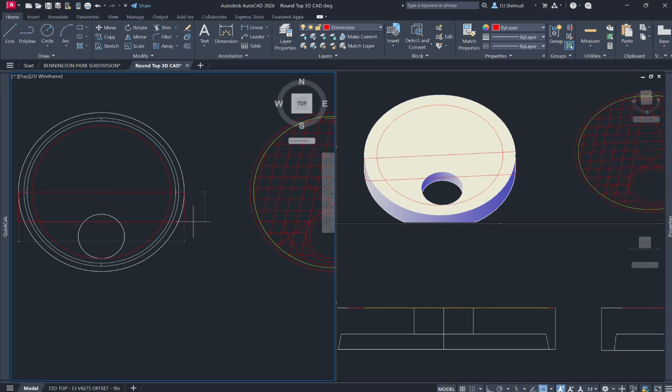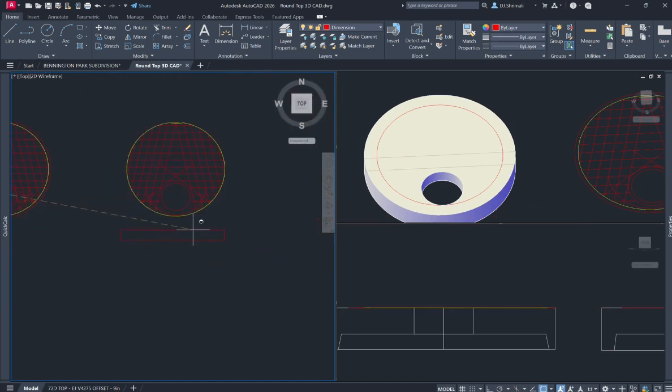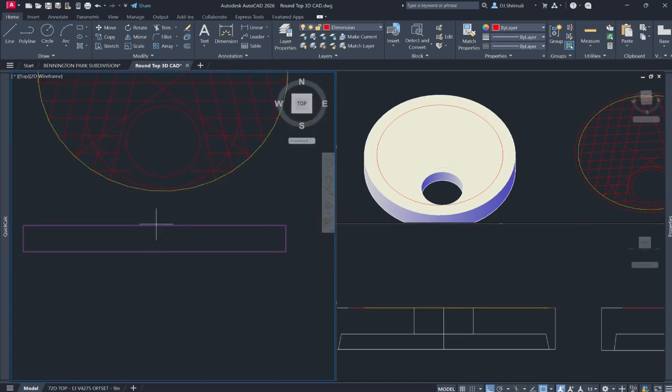Now I'm doing a section view of that. For the section view, I created the rectangle because it's gonna look like a rectangle when you cut the top from the center as a section. Okay, and now I'm creating that opening that we have for the casting. So you see that? Yeah. So I use the offset. I create the center line and then offset the radius of that circle so that you can see that offset line. Okay, and then I offset 1 inch the rectangle, and then I move it from the edges.